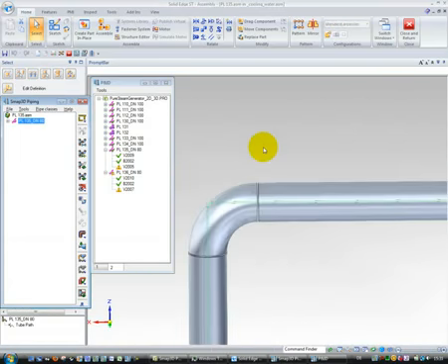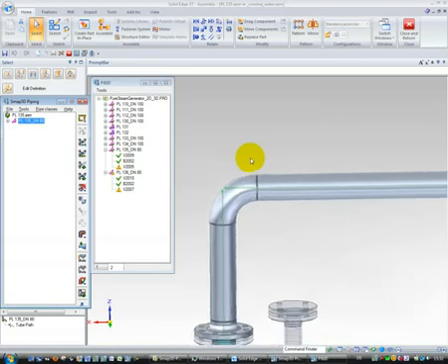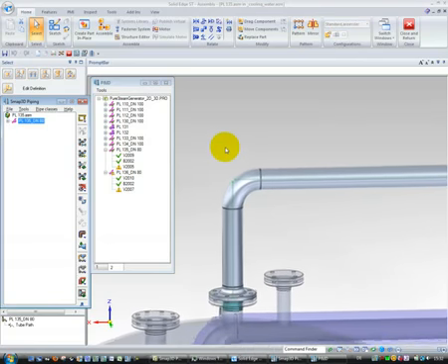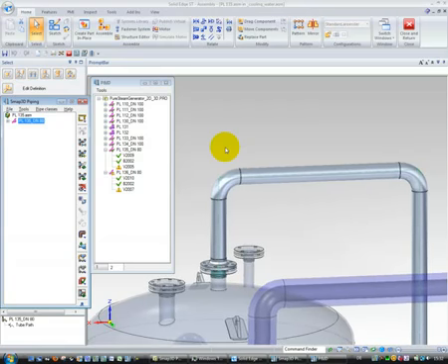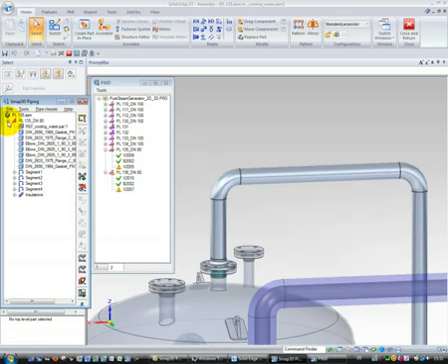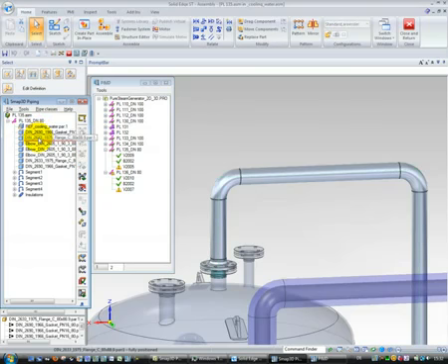If, for example, the used pipe spec contains a definition about the welding split between fittings and pipes, then this parameter will also be used by the software to generate the pipeline. In general, the software always works in the same way. At first, during the generation process, the software analyzes the path of the pipeline that the user has drawn, and then looks at the situations and positions available there.